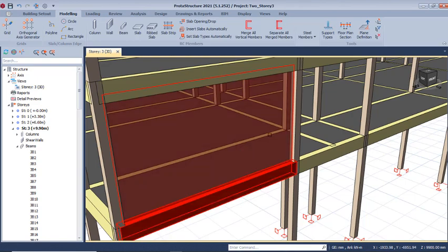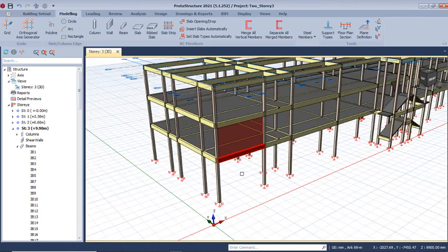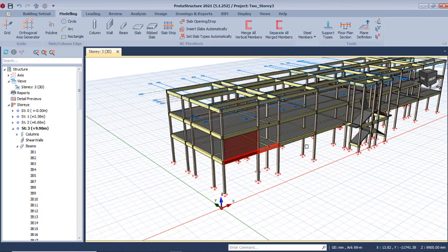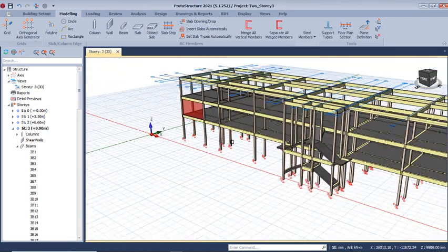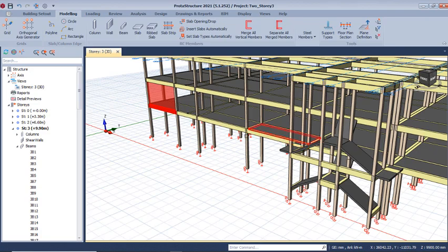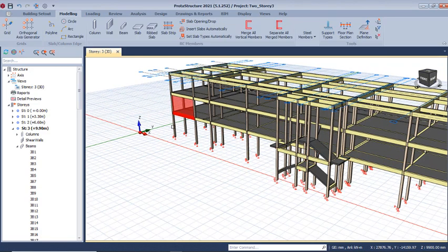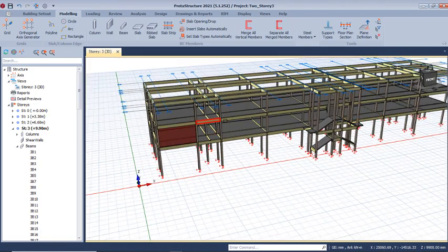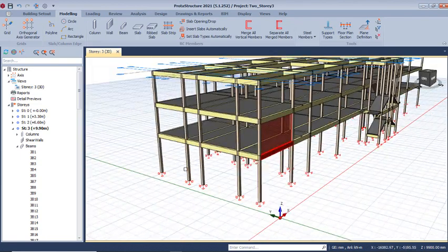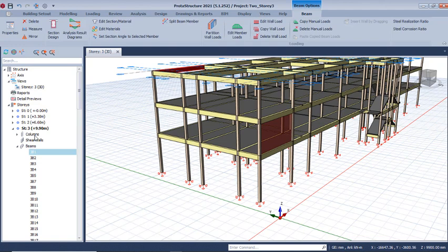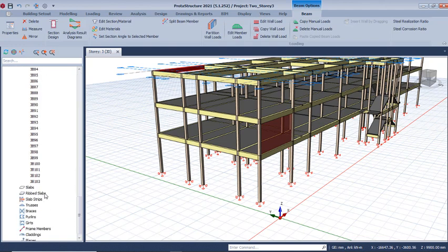Having the wall load just like this, we need to apply it to almost all the beams. There are some beams that are not supposed to carry the wall load, such as these ones at the veranda, because here is a veranda. But we'll be applying to all, for the sake of unforeseen circumstances. You select the first beam, come over to this provisions, scroll down, and then hold the shift key and select the last beam right there.